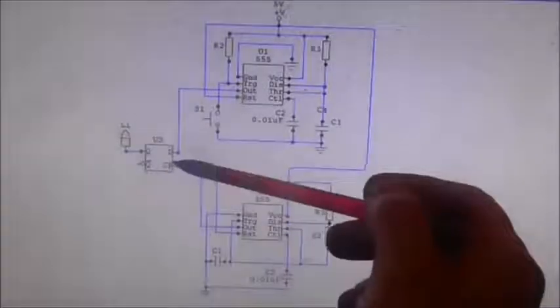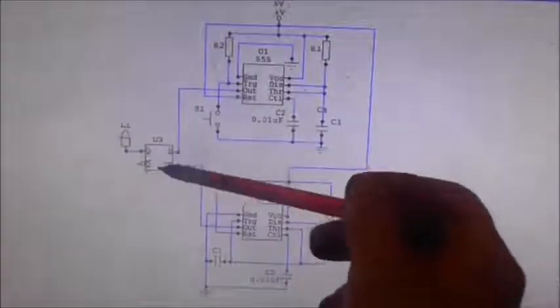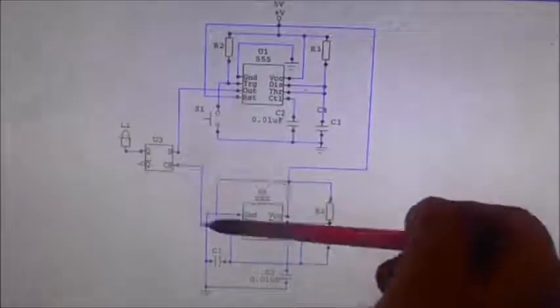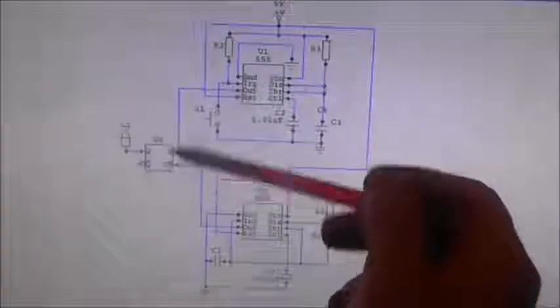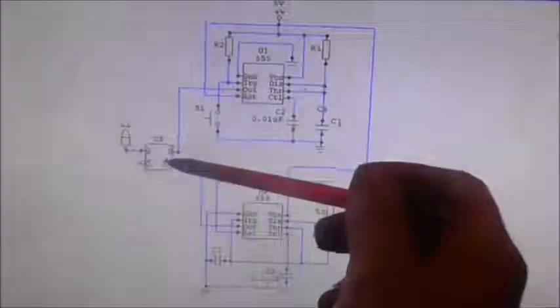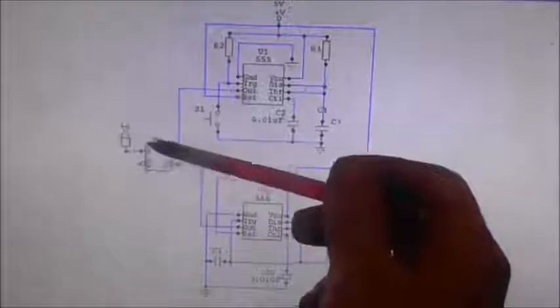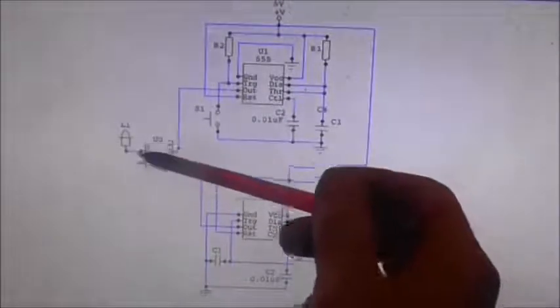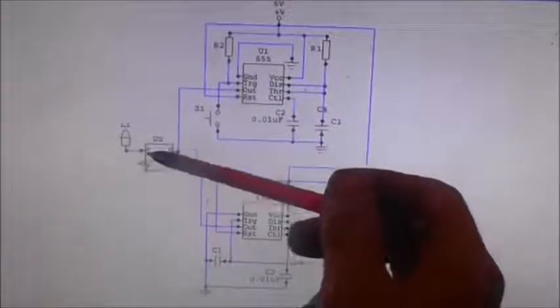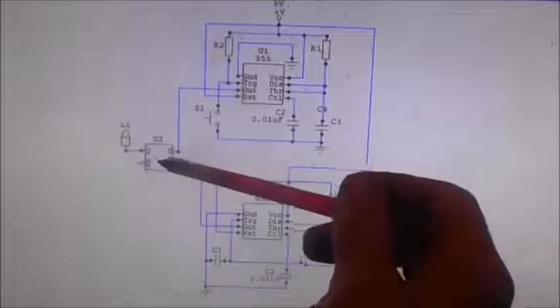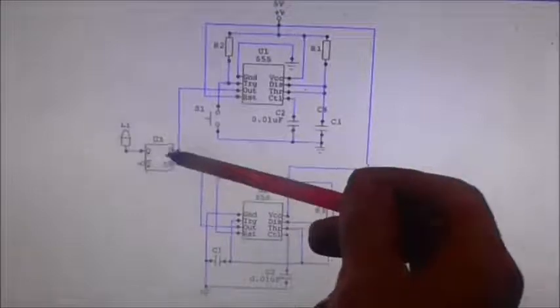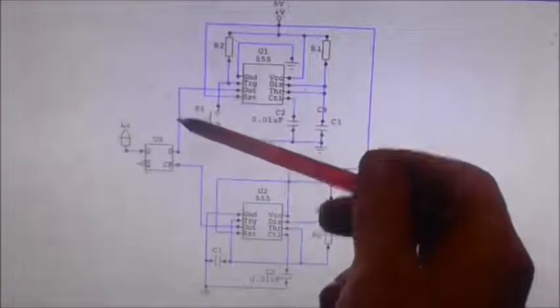The clock pulse, of course, will be 1 and 0, the same thing, and on the rising edge of the clock pulse, i.e. when it goes up to 1, the data will be shifted to the output. There is no bar Q on the chip we're using, there's only Q, so that's where it'll shift. And the data will either be 0 or 1, depending on the state of that.